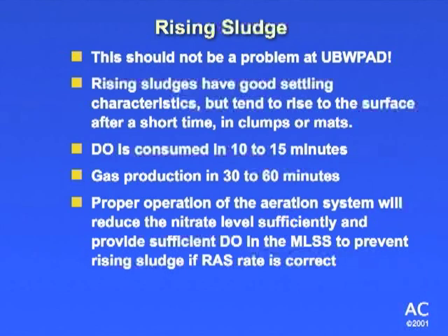So have you guys had any problems with this rising sludge? I've seen it one time, that was because a clarifier collecting system was shut down. When we started it up, boy, it really released some of that. And that's the other thing that can cause it too. You can have rising sludge that's still biological, but it's a mechanical problem that's caused it, where your sludge collection wasn't adequate and you had enough areas in the clarifier that were not being collected from properly.